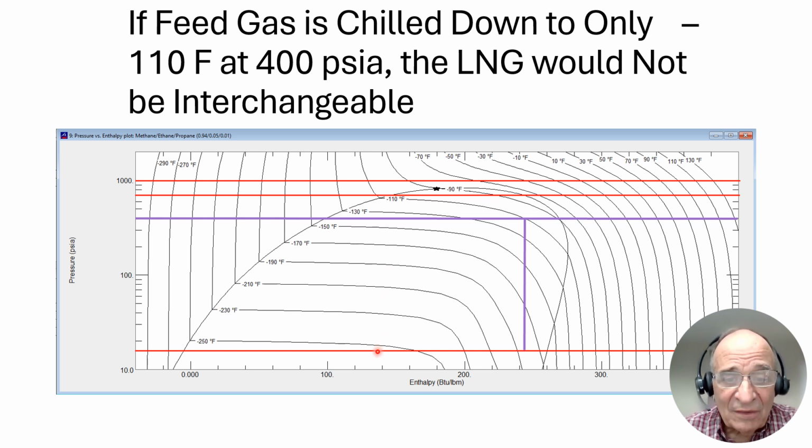We're now approximately 50% liquid and approximately 50% vapor. And we can go even a step higher, but that doesn't buy us too much because it just brings us a little bit more to the left. So it's very critical going from 400 to 700, less critical going from 700 to 1,000 psi absolute.